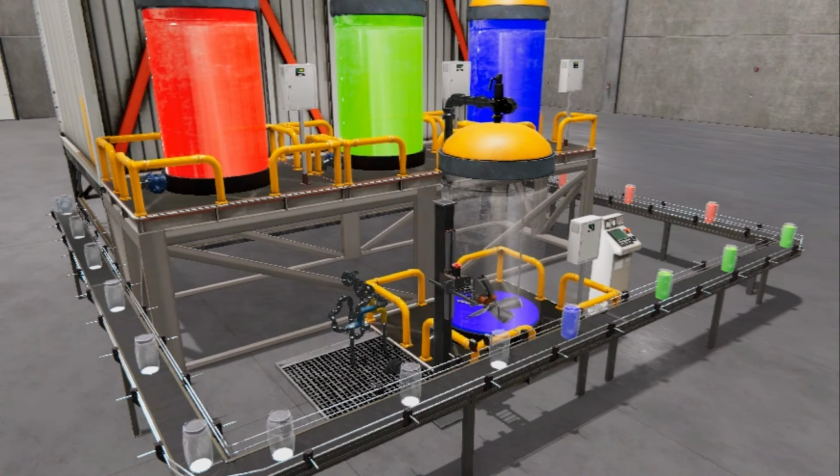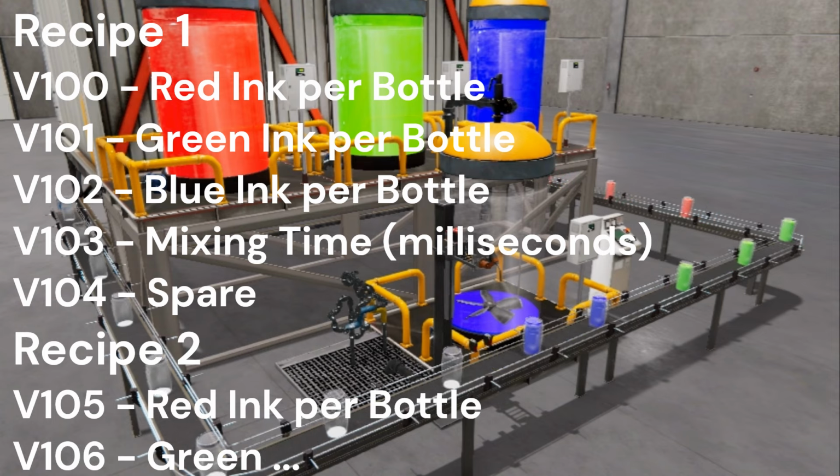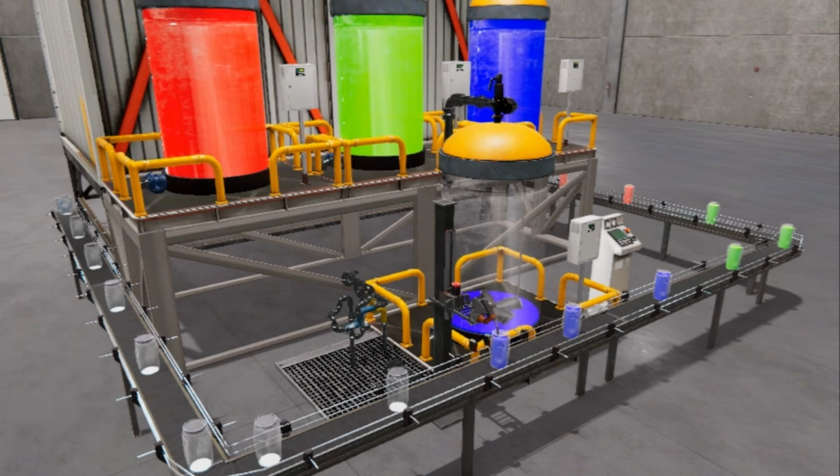The PLC will store recipes for each color that we want to make. We will store these in the V-memory retentive area of the PLC starting at V100. Each recipe will have 5 registers. Recipes will include the amount of red, green, and blue ink required for each bottle to be filled. In our case, this will add up to the value of 100.